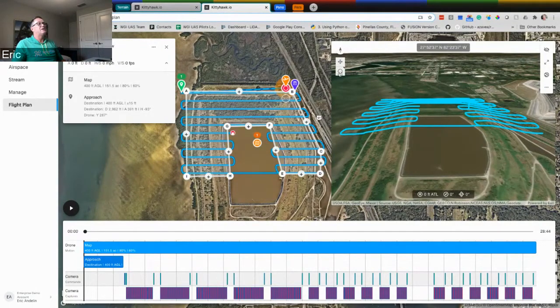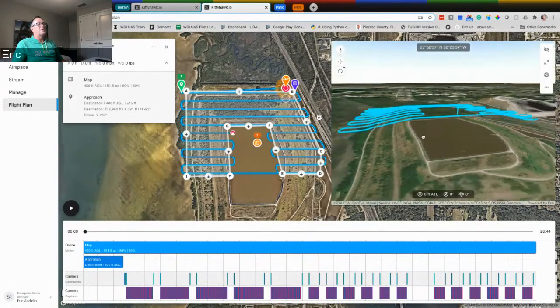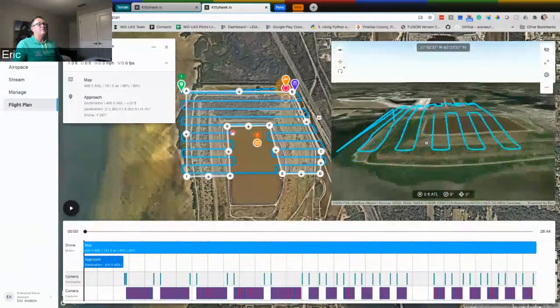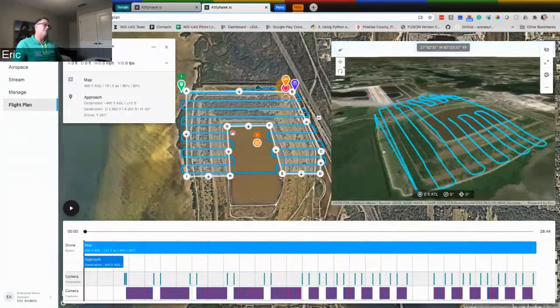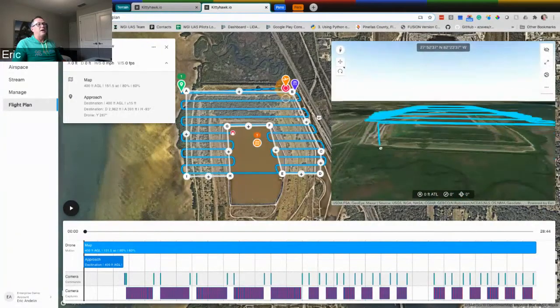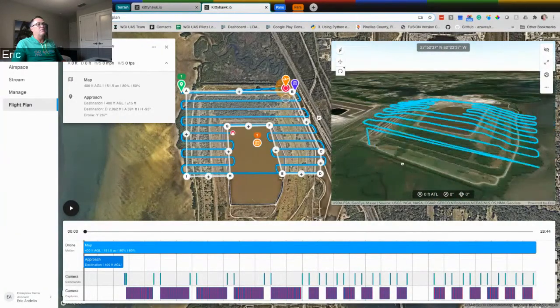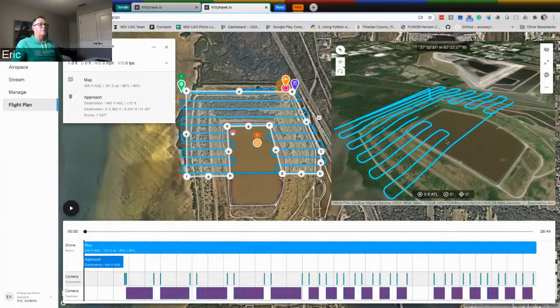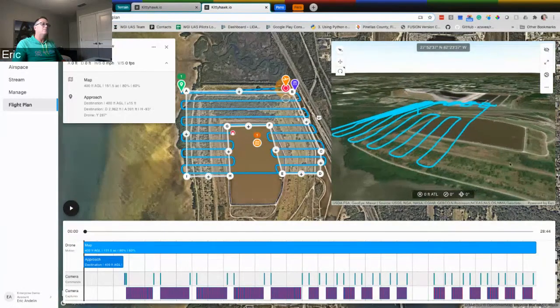You can see here on the map, we actually have the drone following the terrain, which is very beneficial when you're working in elevation, because if you set that at, say, 400 feet and flew 80-60 overlap over that whole project, you're going to end up with much smaller footprints up here than you will down here, and that can wreak havoc on your software that's processing your mapping data. So we have that, we can see it, and we can verify it.